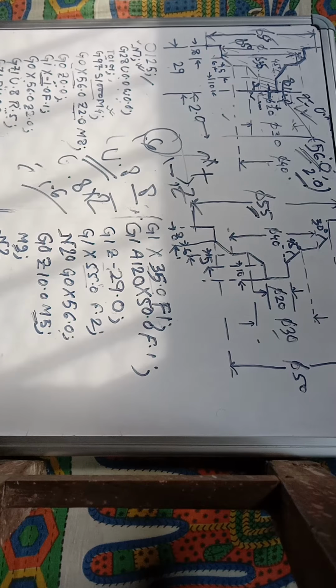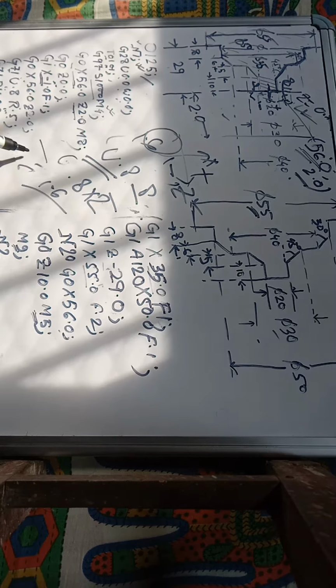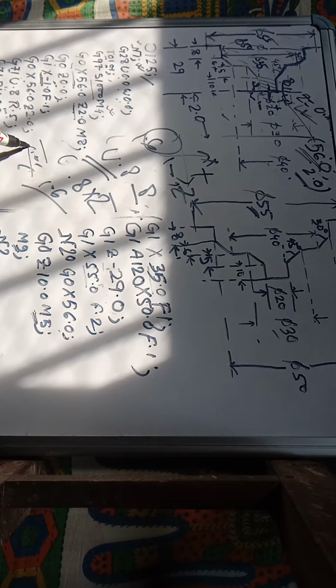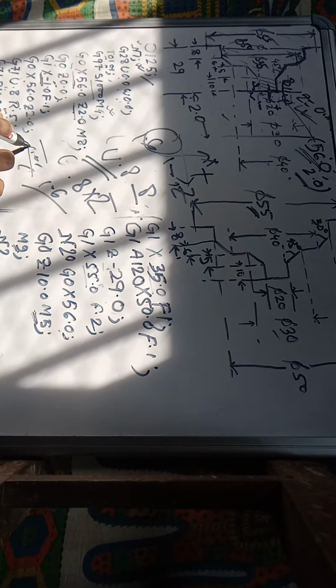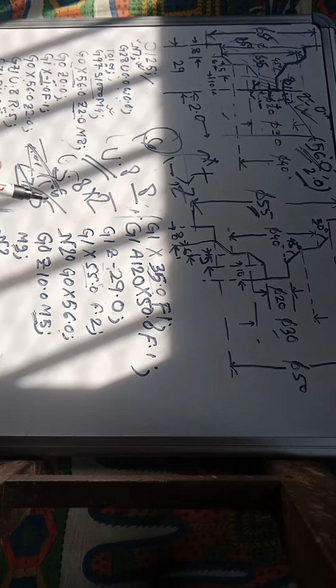After that, R0.5 means the retraction amount. After cutting 1.6 mm, the tool will move backward, and the amount is 0.5. It will move diagonally. The retraction amount is the diagonal move of 0.5. Okay, clear?